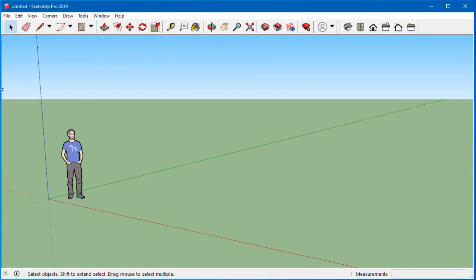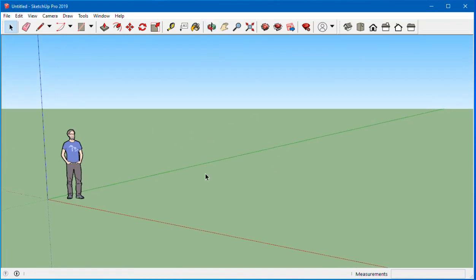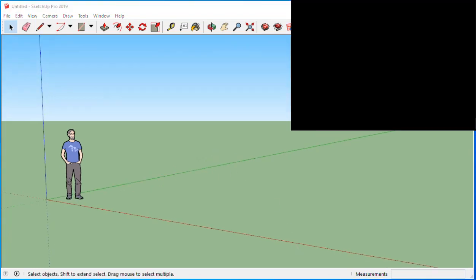How do we navigate in our 3D modeling? In navigating in our 3D workspace, we use the middle mouse button for zoom in and zoom out, and also to activate the orbit command. And we also use the left click when we use the pan command. Let me show you.